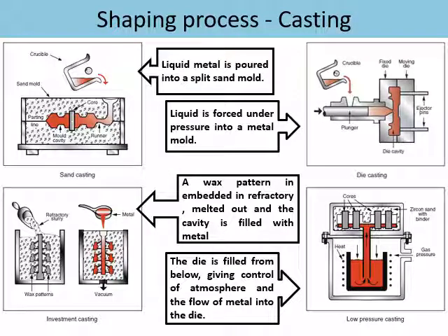This is casting, one of the most common processes, such as you have learned in the manufacturing practice. Casting requires a mold of the product, which includes the inlet to pour the liquid into the mold cavity. The mold can be made from sand, carbon steel, refractory, and silicon rubber. The liquid can be metallic, polymer, such as resin, and also ceramic paste that will eventually harden after filling in the mold.